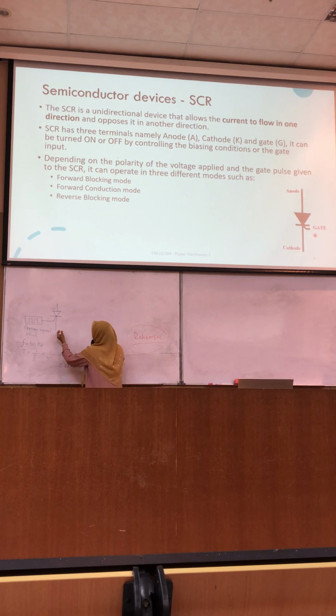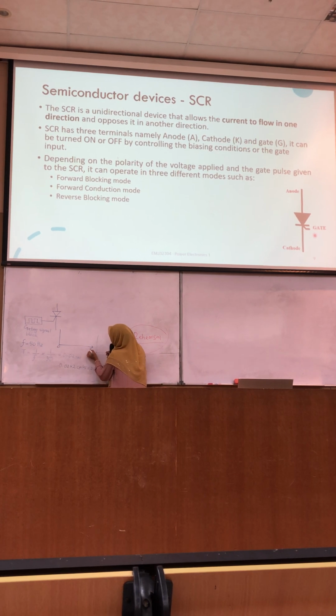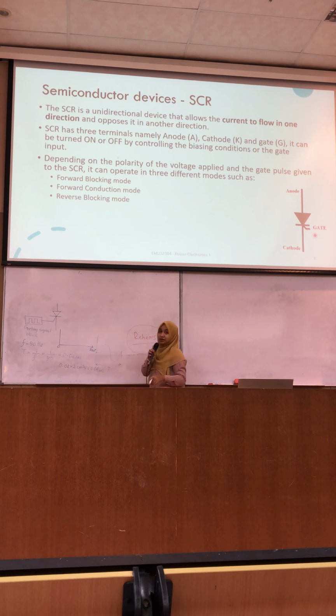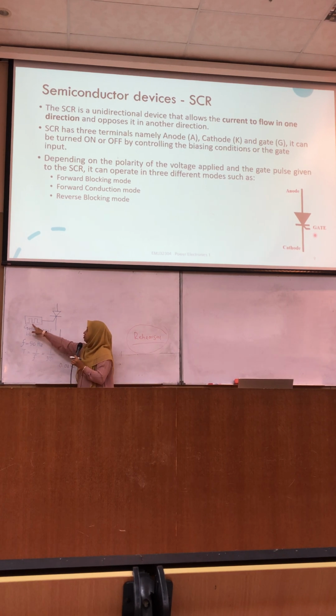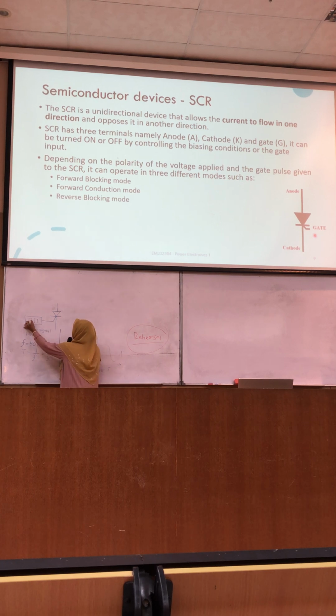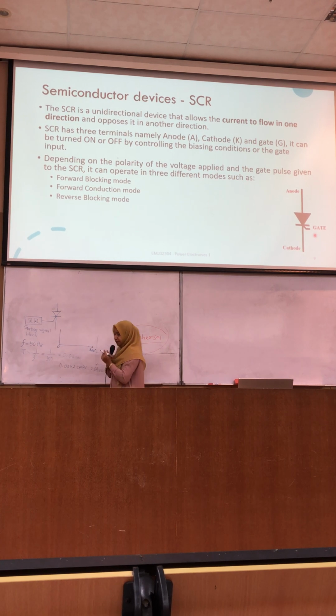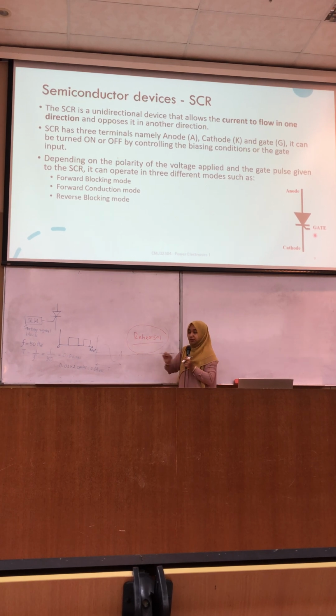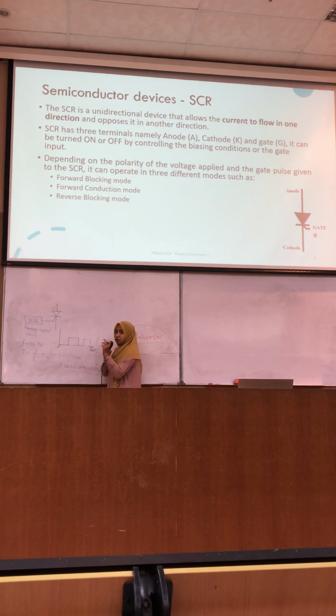okay, we are going to look into one cycle. So one cycle 0 to 2 pi, which is 360 degree, the duration of one cycle. Okay, let's say you want your pulses to be 2 pulses, which is this is 1 and 2, right? Pulses number 1 and pulses number 2. Let's say I put it somewhere around here. Okay. This is in PSIM.